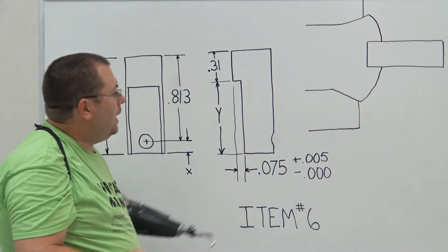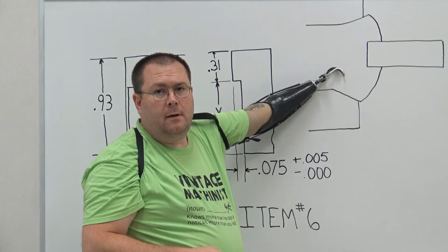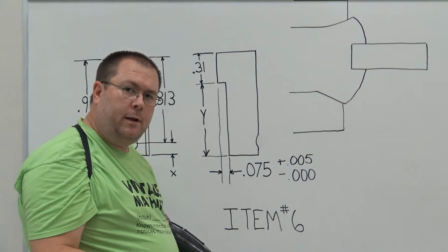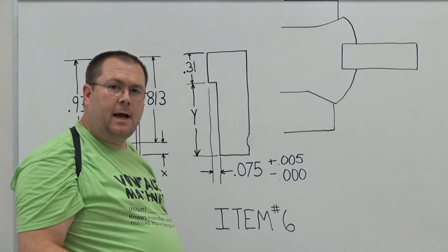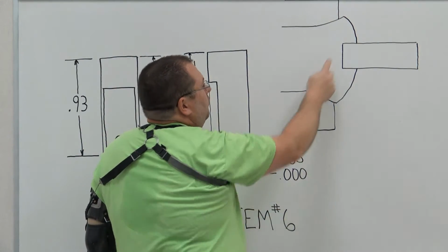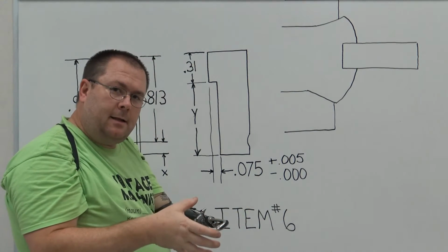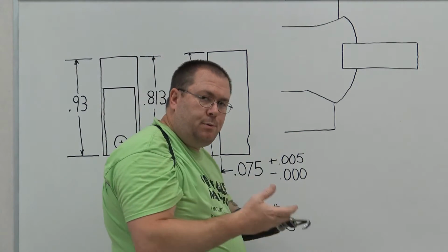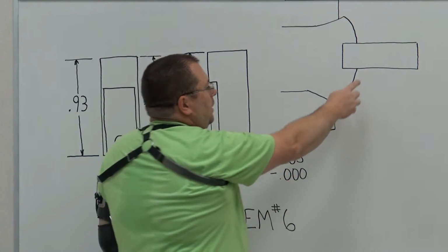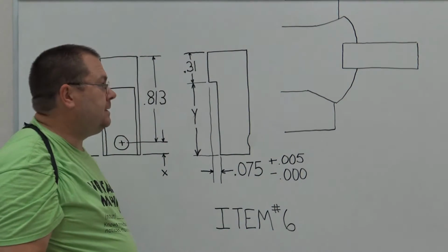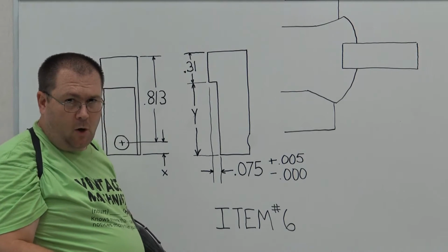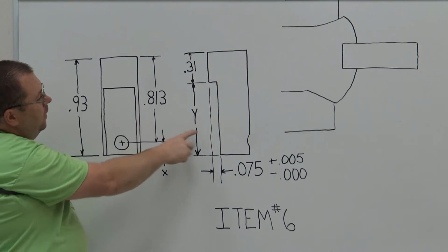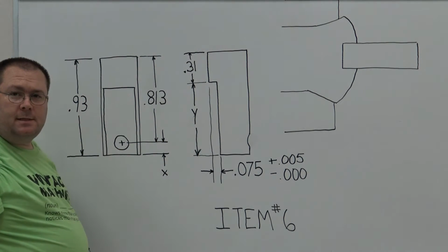What I have sketched up over here is a drawing. This is our component. On the first part of this lab, we learned about a collet called a 5C collet, and this block that holds the outside of the collet and allows it to be compressed. This square block actually allows us to put it in a vise, right? I've got this drawn up here for a very good reason. The first time I clamp this part in, because you don't want to cut into Mr. Bryan's collets, we need to know how big this Y dimension is, right?